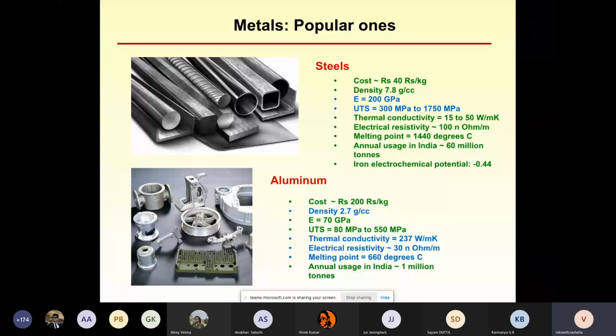Amongst the machine elements I have just listed, which one would use steel with the highest hardness? Bearings. Okay, bearings, the rollers and the raceways used in bearings, they use one of the highest hardnesses in the steel components.